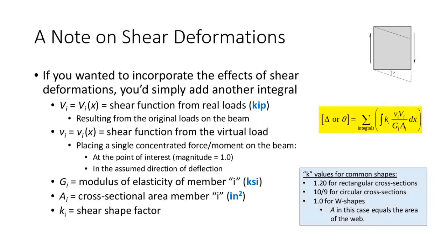I'm curious, some of you in civil engineering materials might have looked at steel rolled shapes and W shapes before. For those of you who haven't, or who are planning on taking me for steel design, we don't really use the term I-beam anymore because of the way we manufacture rolled steel products using modern methods. We use the term W shape. W stands for wide flange section, the flanges being the top and bottom portion of the section. And that constant is going to be 1 for shear for W shapes when you use the area of the web.